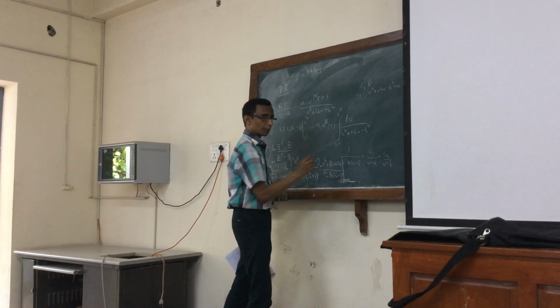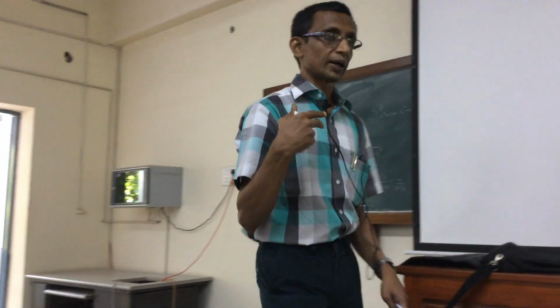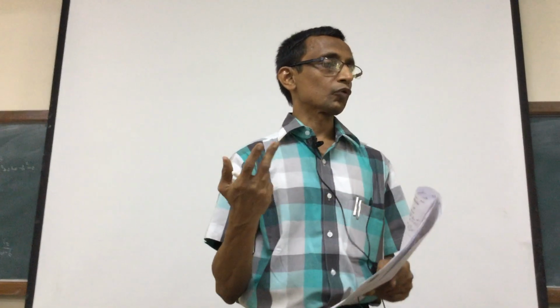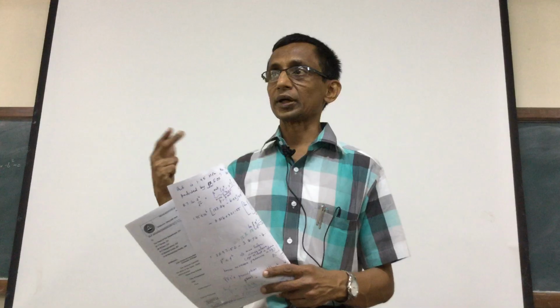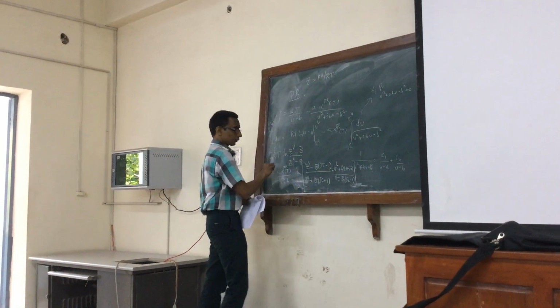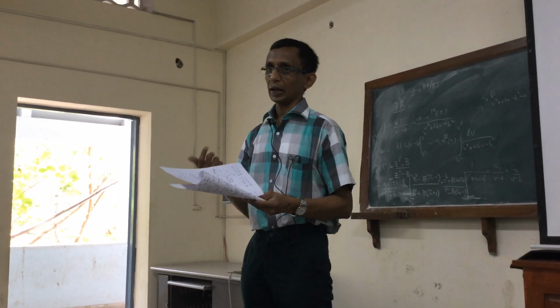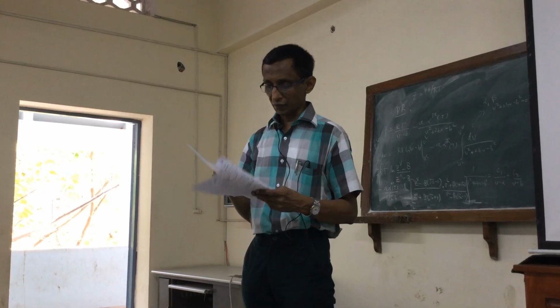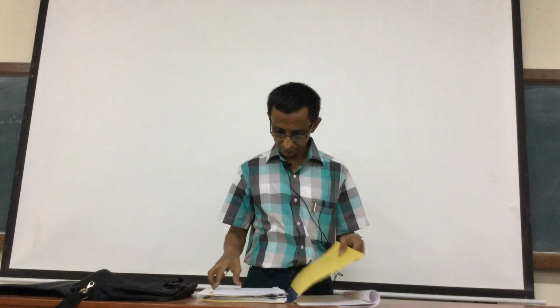And so on. What I want you to do is to verify that the fugacity ratios, FV over FL, will be almost the same for the saturation pressure given, 1.95 or something. If you substitute it into this equation, you will certainly find the two terms are very close to each other. What I mean is this whole term and then the P sat times (VV minus VL). So you have to verify that. We can move on to the fugacity calculation from steam tables.